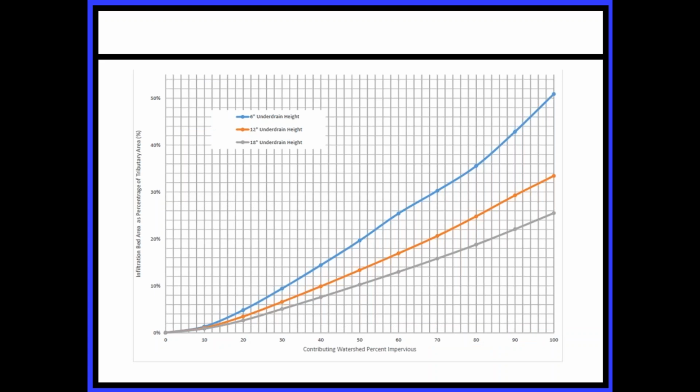So in this particular case, what we looked at was a half inch per hour of infiltration, which would be a Class D clay soil. And we modeled the ability for water over an impervious area and calculated the area needed to infiltrate. The purpose I'm showing this slide for is that there is somewhat of a diminishing return on the depth of that water column.